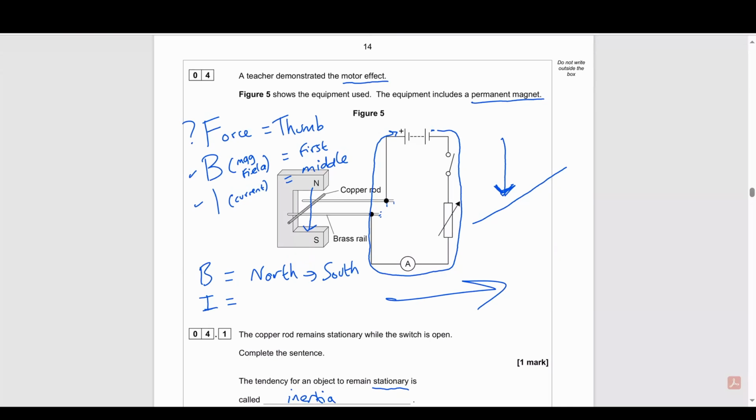Well, one easy thing that we could do is change the magnet so it's stronger. The stronger the magnetic field, the greater the force that's applied to the rod, so it then should cause the acceleration to be greater. What else could we do though? Well, if you look carefully in the circuit, there is a variable resistor that is present. And what does the variable resistor allow you to do? It allows you to adjust the resistance, decrease it and increase it.